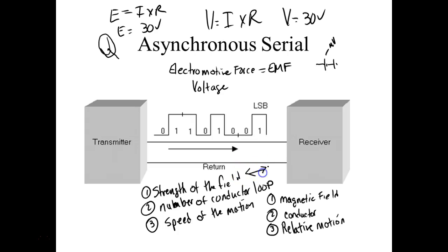And what they're constantly doing is changing the strength. That's one advantage an electromagnet has over a permanent magnet: we can control the strength of the magnetic field. So as your car slows down, the output of your alternator tries to go down. Your regulator increases the strength of the field, and it keeps your voltage out of your alternator a little over 14 volts. We say we have a 12 volt system, but it's not. It's basically 14 volts, but it'll run on 12 volts, because anytime your car is running.